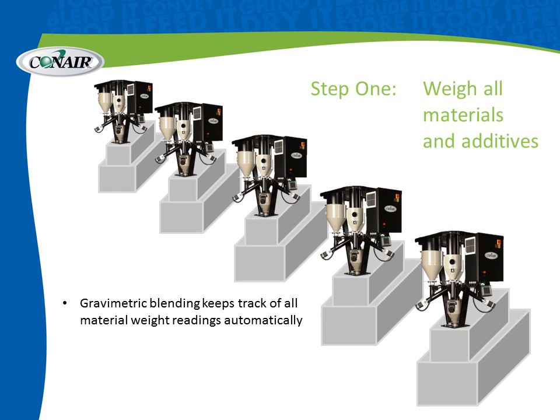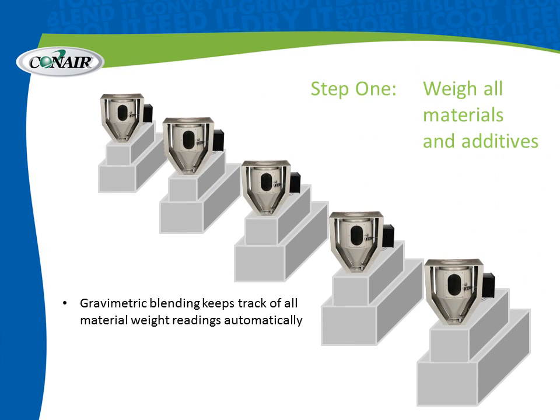The gravimetric device in use could also be a continuous blender. Now the ones we show here on these little processing machine shapes are actually loss in weight type blenders, typically used in extrusion. And as we consider gravimetric precision, we can get right by blenders and we can use just simply weigh hoppers. Weigh hoppers will weigh whatever amount of material passes through them from whatever device is above them to the processing machine below.